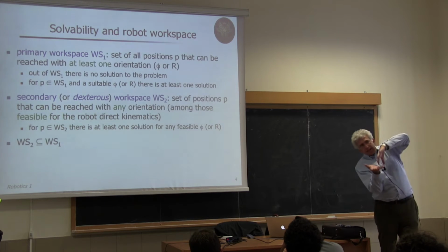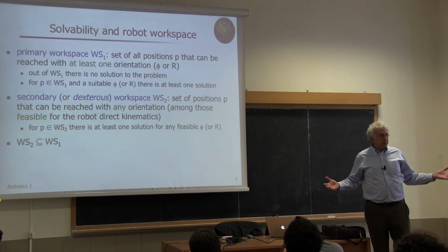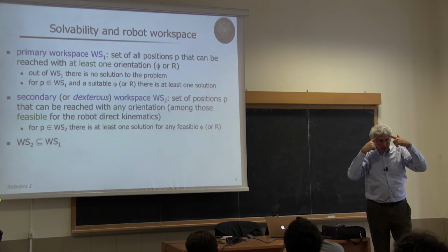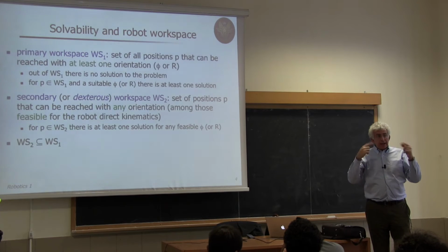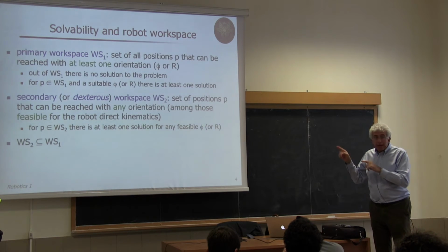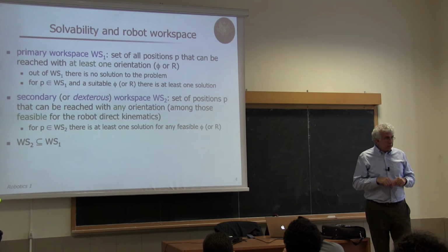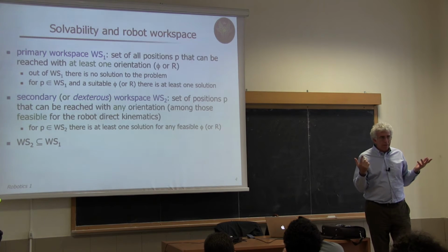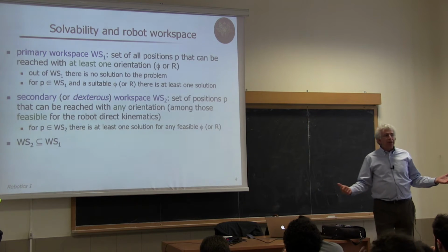And if I'm asking to go out of plane, I will never have this possibility. But in that case, I should think, okay, this is a planar robot. It can have only orientation around one axis. So I can define a point in its secondary workspace if I realize in that point any of these orientations around the normal. Not those that the robot can anyway not realize.